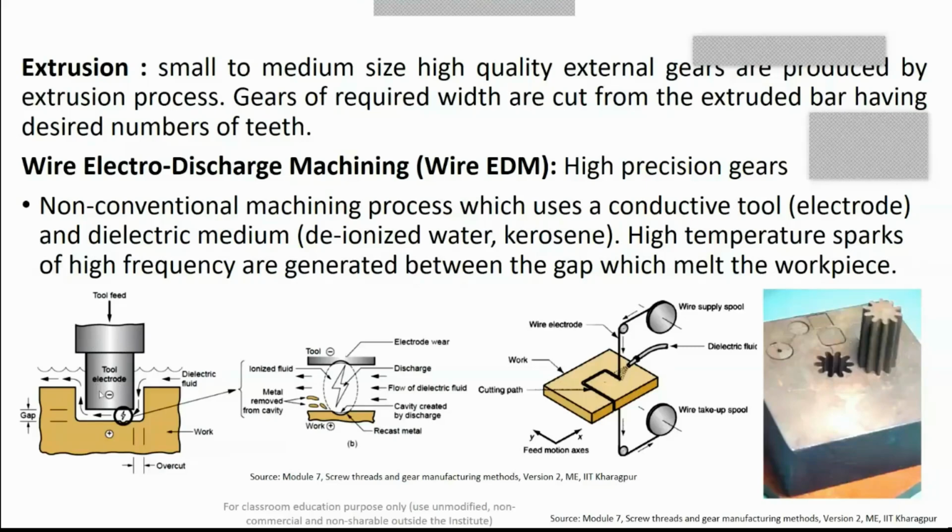But you see that on the tool electrode the polarity is negative, and on the workpiece the polarity is positive. So the maximum amount of heat is going to be produced on the workpiece surface, which has the positive polarity. With the course of time, this wire wears off. Sometimes it breaks while doing the operation, so such types of problems arise.